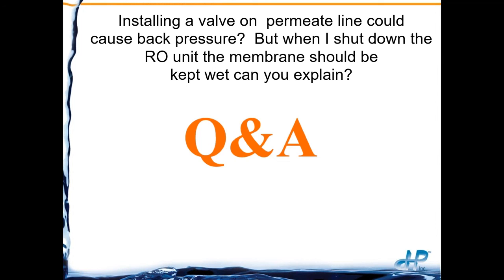But that being said, we don't recommend putting ball valves or shut-off valves on the permeate side, because eventually you are going to have an issue with that permeate back pressure.